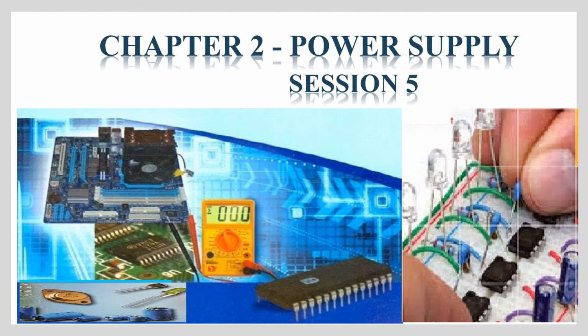Then followed by the filter circuit. The output of the rectifier is known as pulsating DC. We didn't get a constant DC, but there are some unwanted AC components. To remove this, we use a filter circuit. That is nothing but ripple. We have seen filters. There are different types of filters: capacitor filter, inductor filter, then inductor capacitor filter, then the pi filter. We have seen the T filter and series RC filter, followed by a regulator circuit.